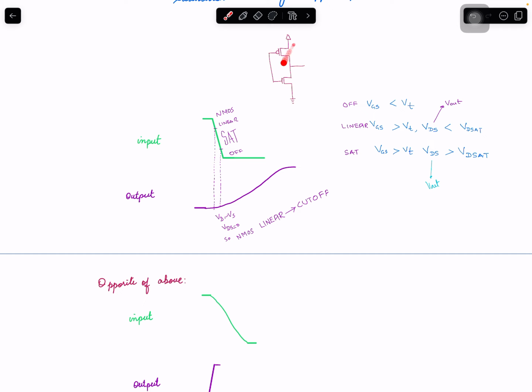So our CMOS inverter, this is the input we are giving it here, and this is the output. You can see that the input goes from high to low. That means NMOS was on and the output was grounded, so this was at 0. And now what's going to happen is NMOS is gradually, in a typical operation when input goes like this, output will go like that.